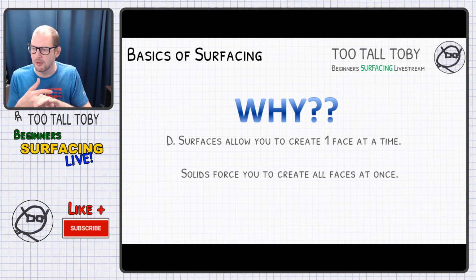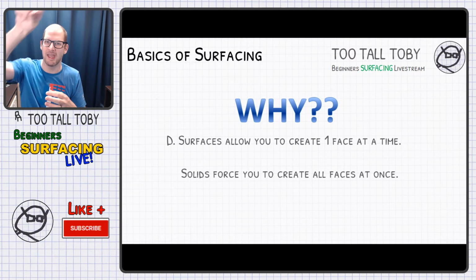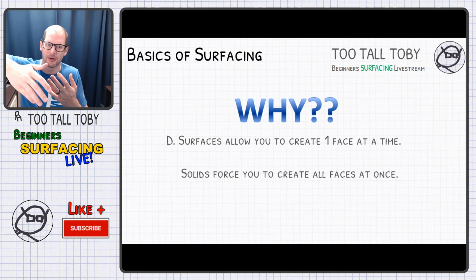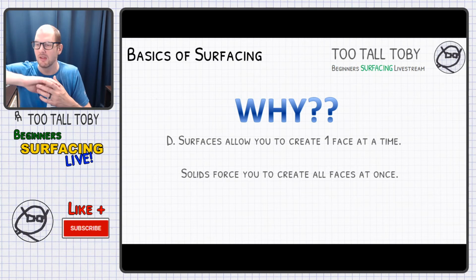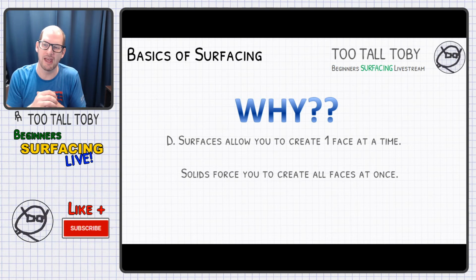You can use surfaces to patch certain regions of your models, like we did when we deleted the face on the top of the cylinder, and then we added a little spline up top, and then we did a fill surface to lay over the top. So you can add a single face at a time, and then you can patch that all together.